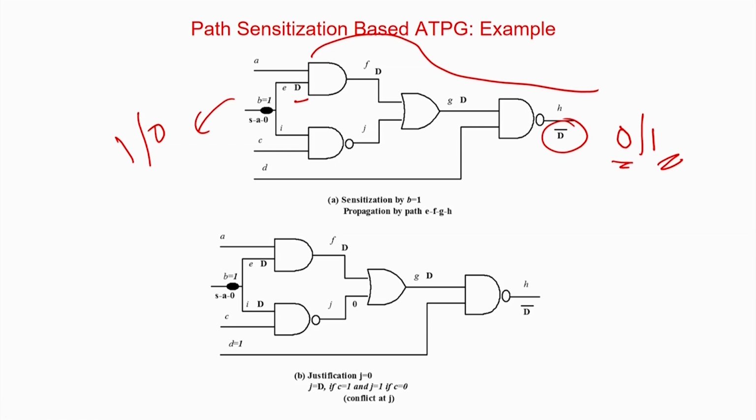So this is an AND gate. We all know that for AND and NAND gates, to propagate the value to the output, the non-controlling input value is 1. Because if I make this line 0, the output will be 0 by default. So the fault effect propagation will be lost and you are not going to see any difference. If I put a 1 here, the answer will be 0. If I put a 0 over here, which is the controlling value, the output will be a fixed value. Then actually nothing you can observe. For both normal and fault cases, the value will be the same.